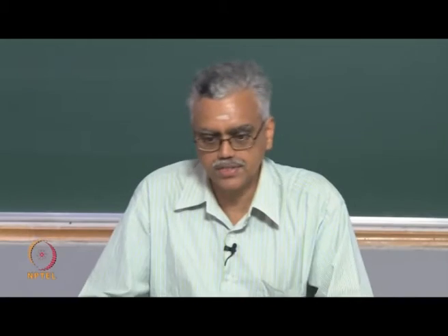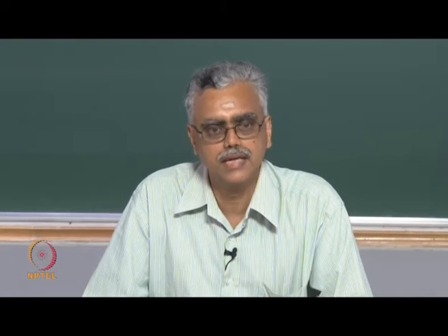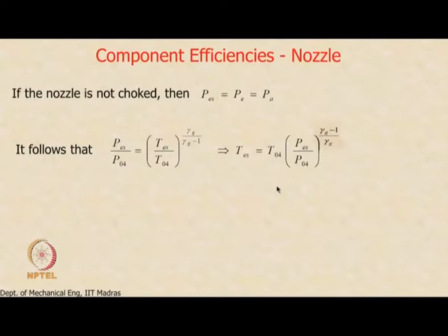So, when you want to evaluate the thrust from this engine, what quantities do we require? We are going to show that next, but we have already talked about thrust and other things. There are only two quantities that we need at the exit. Those are velocity and exit static pressure. So, now in this case I know the exit static pressure and I need to calculate the velocity VE, right.